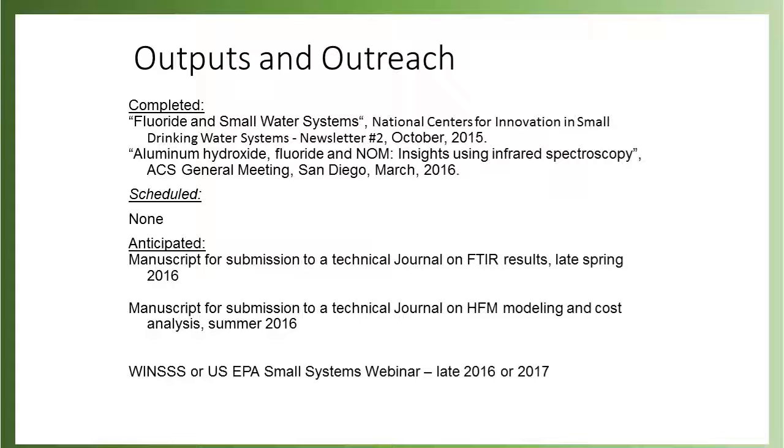But relative to the comment that Bruce made, the idea here is that you're using the ED to make an initial separation. Then you're actually using both streams again, but the RO is only using the one stream, so that you're basically allowing the RO system to operate much longer without fouling.